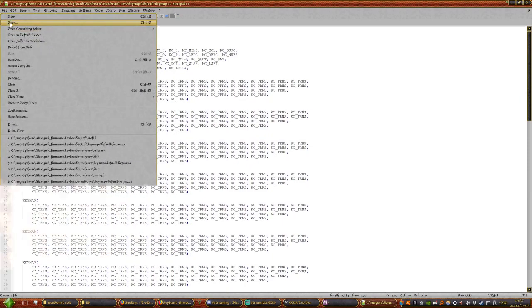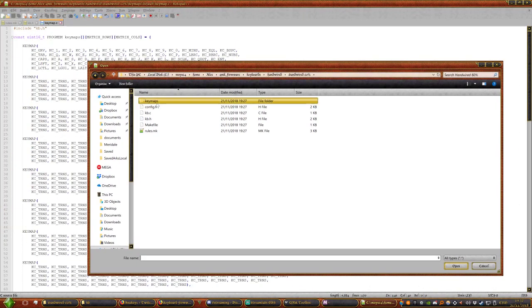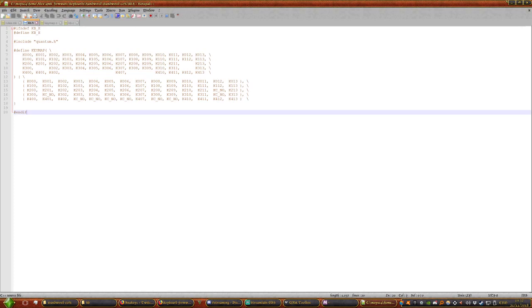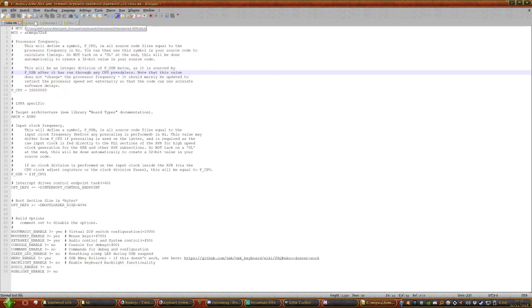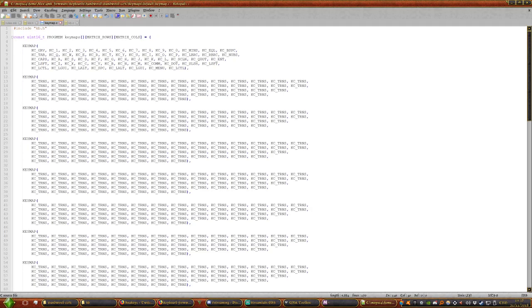So now I'll open up the other two folders. We've got KBC, which is just simple really, it just says include KBH. KBH is the main file, because obviously that defines exactly where the switch positions are. So you can't program your keymap to a switch that doesn't exist. You'll see that these gaps down here correspond with the KC_NO in the ones below. So that's basically the way that the files are interlinked. You'll see at the top that it says include KBH.